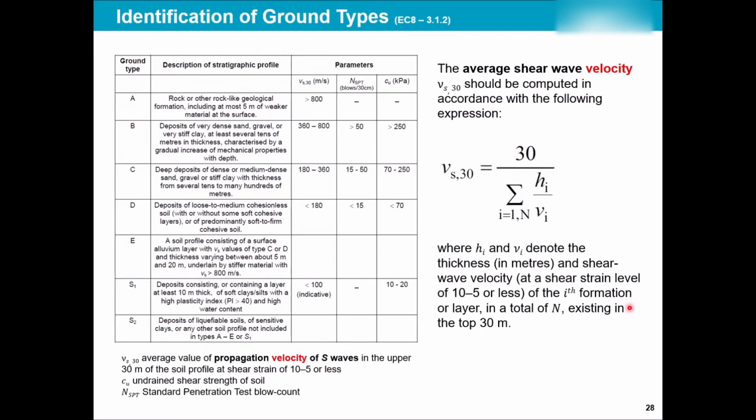So Eurocode has applied thousands of earthquakes and has designed response spectrums. Those response spectrums, if you remember, were categorized based on ground type, from A, which represents rock, all the way to E, which is very soft, loose soil.